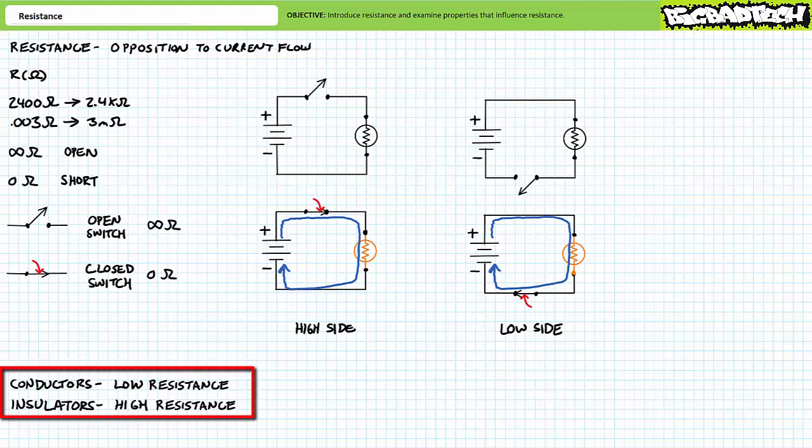In this spectrum from 0 ohms to infinite ohms, we could arbitrarily divide things into one of two classes. Conductors are devices with low resistance. Insulators are devices with high resistance. It'd be a terrible mistake to classify a conductor as something that conducts electricity, and an insulator as something that does not conduct electricity. I'm here to tell you that by that definition, everything is a conductor.